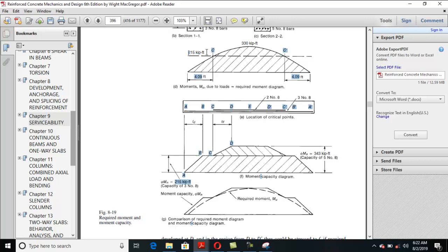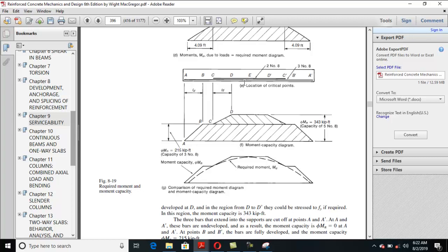They cut 2 bars, and they determine the moment capacity, which is 250. Now for 215 they determine the cutoff distance, that is 4.09, from the same equation which I did in lecture 9. Clear? And he explained it in more detail, as Cormac did in this diagram.